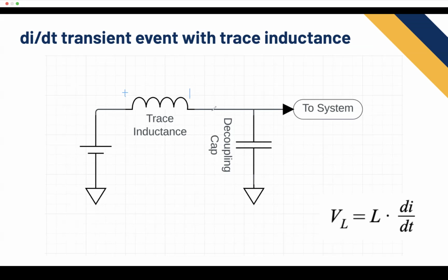And then your voltage here, if we say this is like a 12-volt battery, your voltage here could drop quite significantly if your inductance is too large. So let's say your voltage drops because of this inductance to, let's say it's really bad, like 9 volts, or maybe somewhere between 7 and 9.